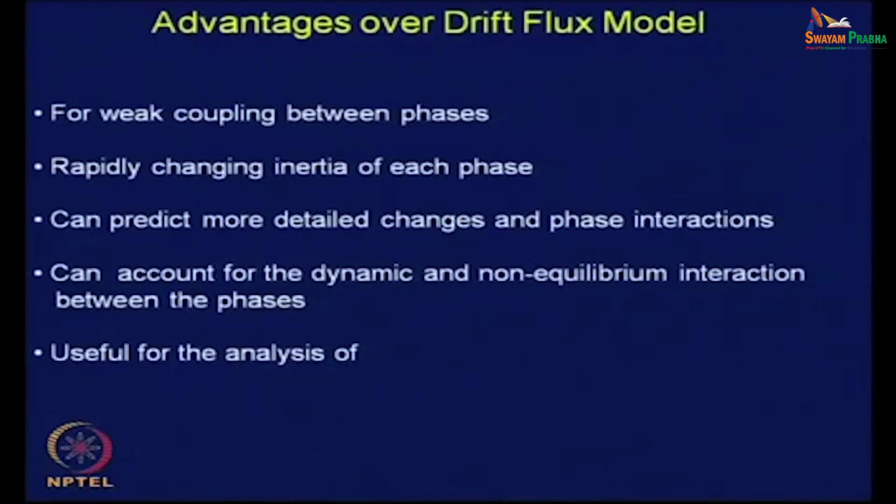Now, the advantages you have over the drift flux model. In this particular case, it is quite evident that the interaction terms determine the degree of coupling, and therefore they determine the transfer processes in each phase. If these interfacial exchanges had not been incorporated in the balance equations, then the two phases would have been essentially independent and could be analyzed by mere single phase flow equations. When we start the analysis, we will find that the only difference between single phase flow equations and the two fluid model equations is the interaction terms.